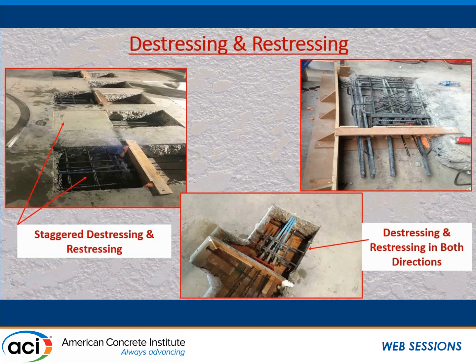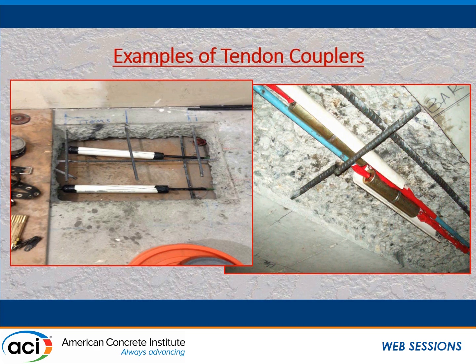On the far right, you can see this is right at the corner of a slab. The amount of mild reinforcing that has to go back in after you open these up is sometimes pretty stringent. We found some challenges at times. The last thing you need to do is have so much congestion there that you create another problem in your repair. So the use of couplers, for whatever reason, I'm not even sure why our field guys, we go more to extraction now than we do to coupling, but some of the times, installing couplers is a solution.